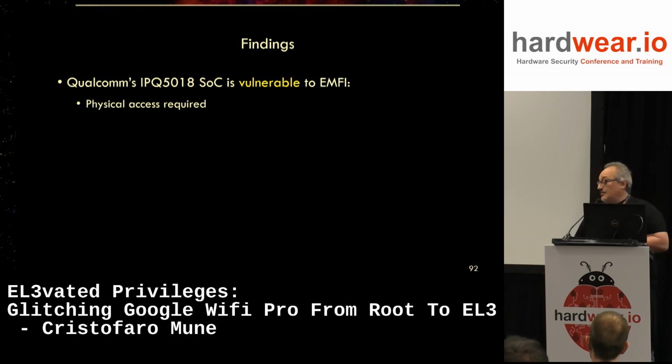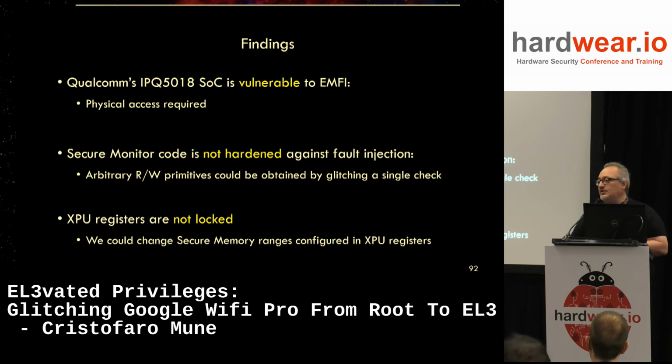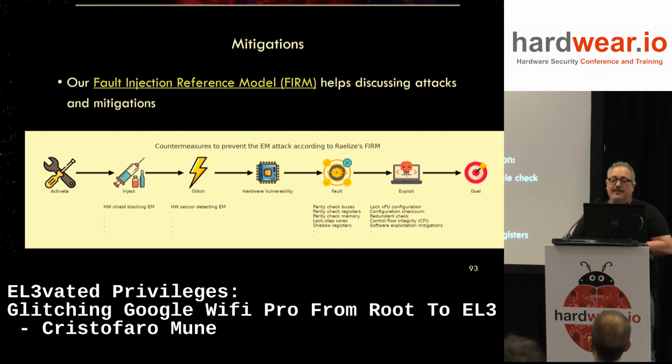So basically, conclusion: the SoC is vulnerable to EMFI. Physical access is required. This monitor code is not hardened against fault injection. Again, not surprising. The surprising part may be that you could have locked the register of the XPU, because it's a feature you can use. At least we think it's possible for these XPUs, because some others can be locked. This would have prevented us from changing the value.